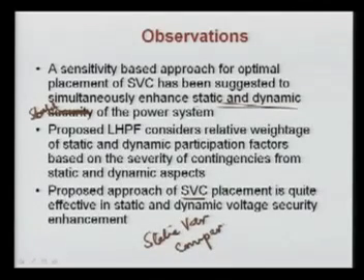Basically, we are changing the impedance, and it is a shunt device compensator. Another shunt device that people are discussing very popularly nowadays is the StatCom. Function-wise, StatCom is similar to the static VAR compensator, or SVC, but StatComs give better performance than SVC at several locations. They are very important, but StatComs are very expensive compared to your SVC.